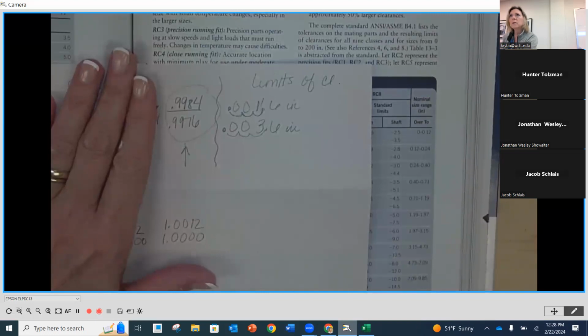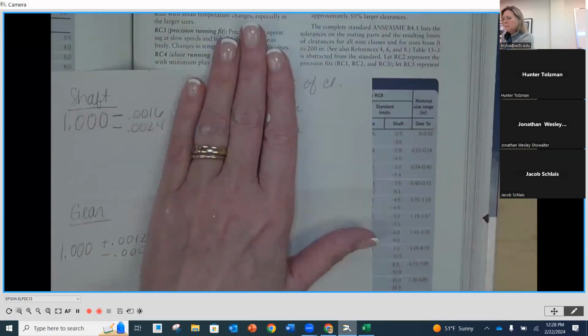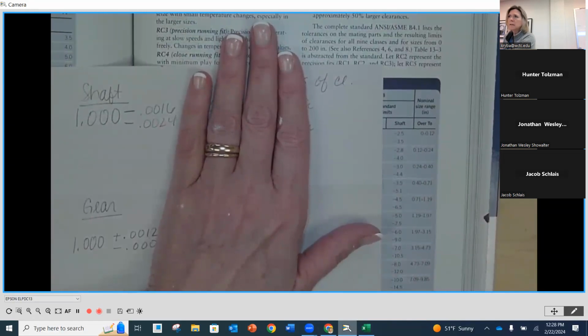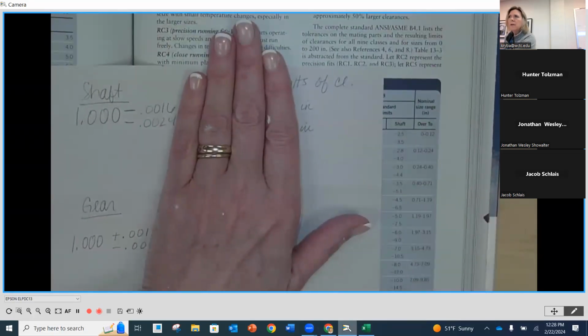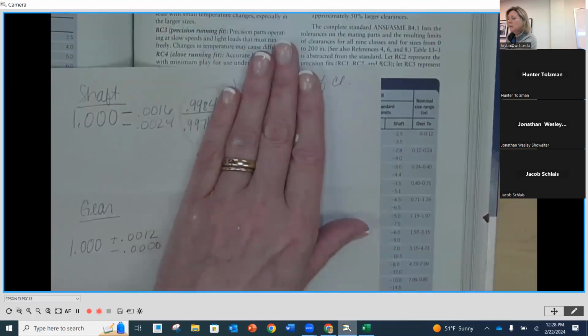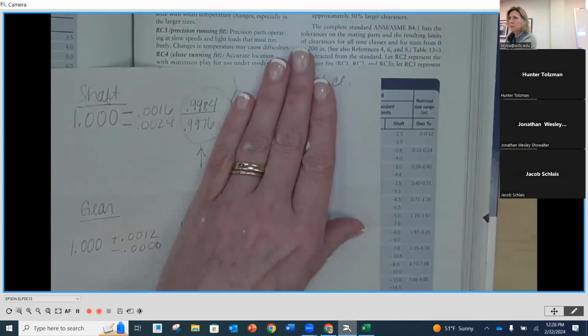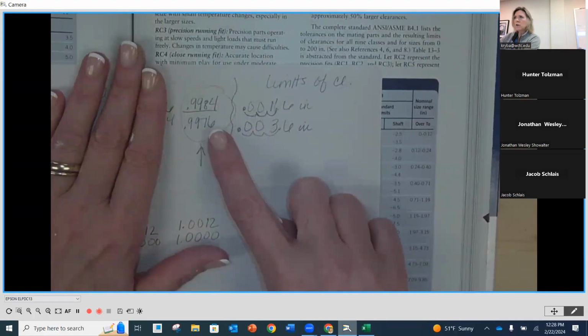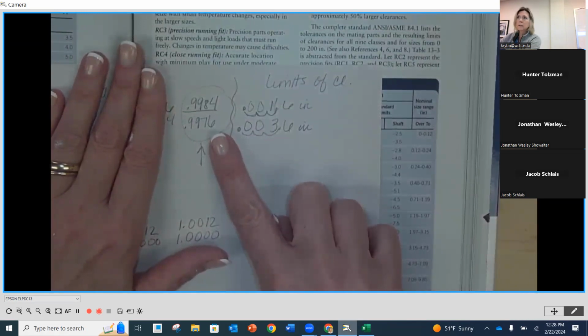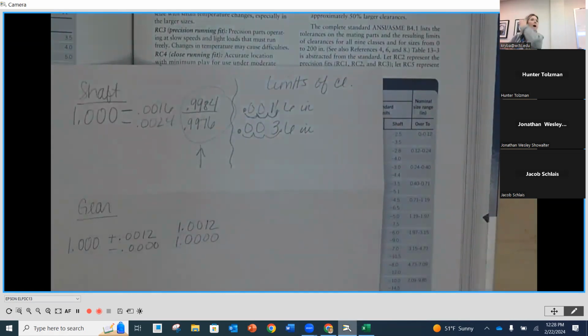You want to always think of who's going to be making this. You can do a plus and a minus tolerance, but remember, this requires somebody to do that math in their head or on a calculator. And there's a step in between where, in translation, you might not get the actual numbers. So especially when you have things that are really accurate, on the drawing is where you would want to actually put the limits. I wouldn't use plus and minus, again, for that reason. Other questions?